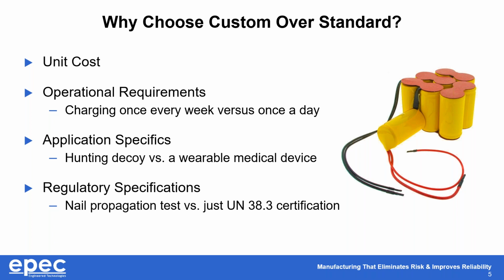And once a week, that's going to last you maybe 4 to 5 years in terms of life cycles. But if you need to charge it once a day, you really need to understand and manage the BMS to be able to ensure that you're not overcharging and over discharging and reducing the life cycles.